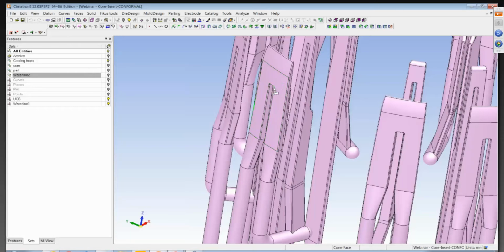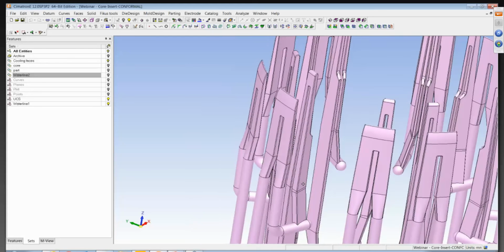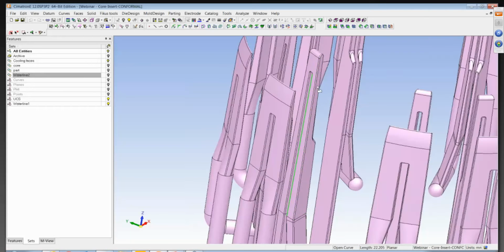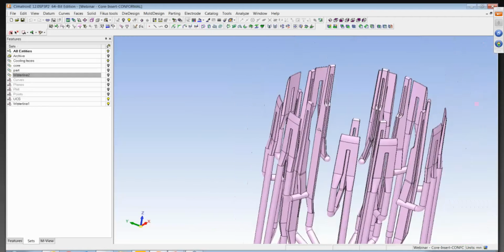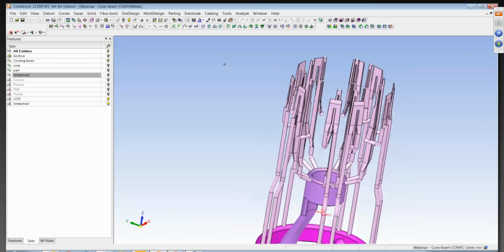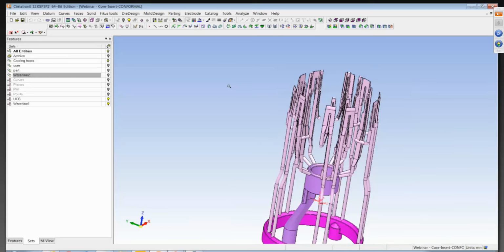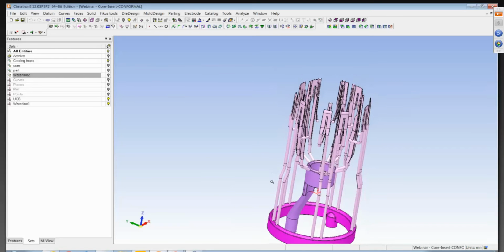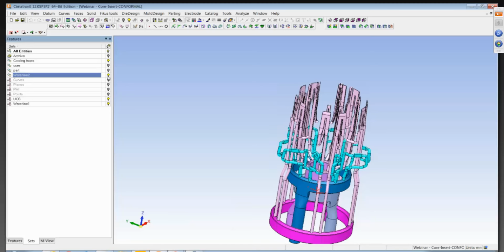Then of course it had to be built so it could wrap over the top, come back down, and then it's set up again to go into the next core, and here we're getting into that super narrow area. What that means is that the water flow is going to slow down here. There's just no getting around that. It's going to slow in those areas, meaning it's going to slow in the overall time it takes the water to get up, all the way around, and then back down through the exit down here in the center. It's going to run slower than this water line.